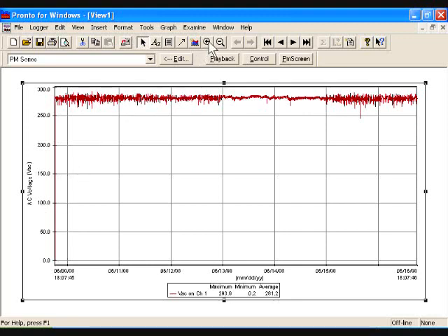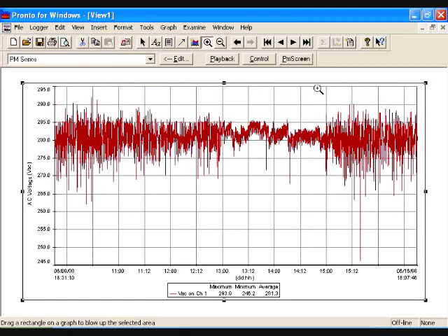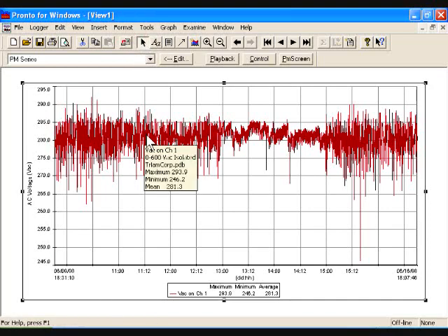However, by using the zooming tool, which is the plus magnifying glass here, if you click on that, you get a magnifying glass, and you can just zoom out the very few first seconds of this recording, and then the voltage will appear as it would normally be presented to your eyes. Now, if I go back to the arrow and touch the graph line now, you'll notice that the minimum is 246 volts, which is what was the reality of it once it was hooked up.